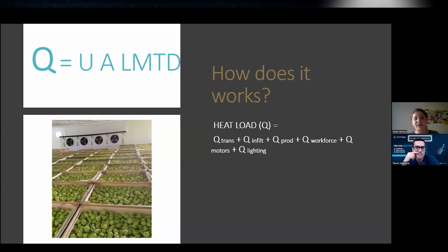The capacity, for example, is the heat load that the heat exchanger requires. So the required capacity is defined by the application needs, of course. In this case, I will talk about cold rooms and also condensers. In cold rooms, it's important to consider the inlet temperature of the product, the storage temperature of this product, the infiltration that you can have, the amount of product that you have, the heat produced by the motors, lighting, persons that will be working there, etc.